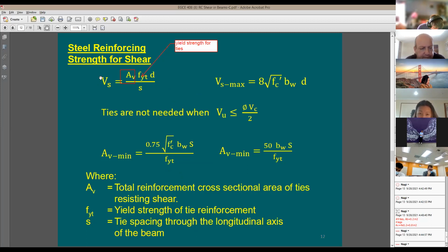Okay, good. Let's say I was working on a beam section and the shear was really in bad shape. I mean, the shear resistance was not good. So I started to add lots of reinforcing bars. The ties, I made very closely spaced. I put number 4 at 3 inches spacing. I dumped lots of ties. You remember what happened when we added lots of rebars at the bottom of the beam for the flexure, right? We had a problem with this phi factor. The phi factor starts to drop down. And here we have a limit.